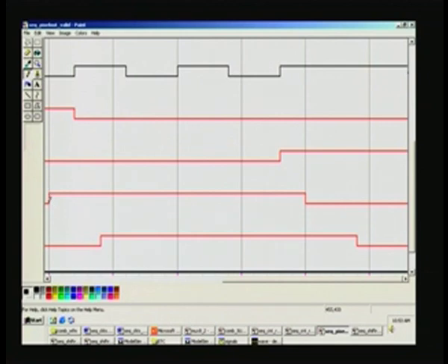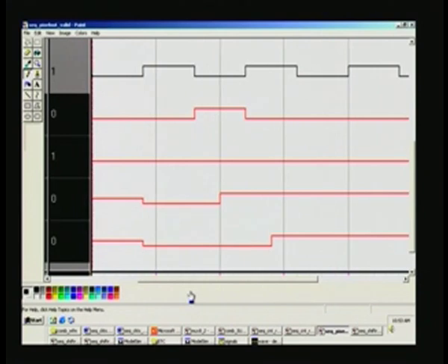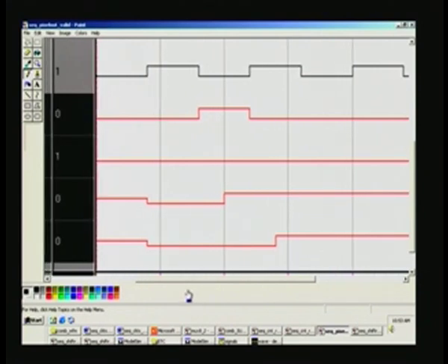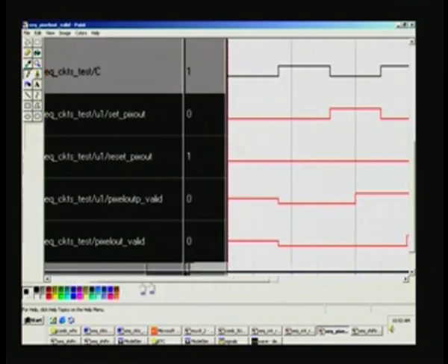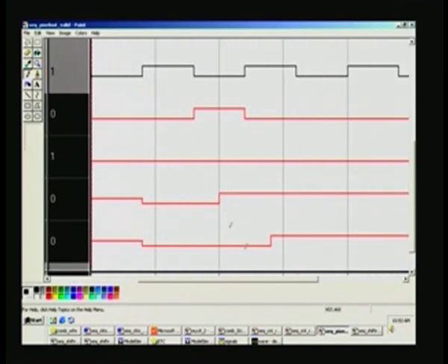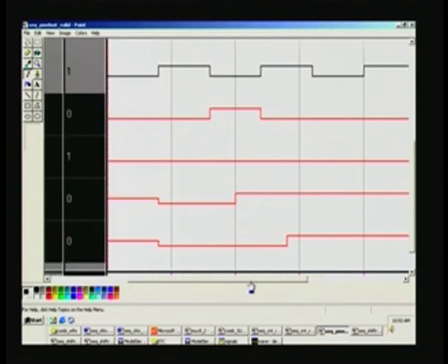So, you have seen pixel out P valid and this being staggered just by 1 clock pulse, and if we explain this pixel out valid, why it is happening here and why it is going low here, that would complete this 2 registers used as in a pipeline, or it's just to create a delay as such. So, now let us see why it is going high. It is going high here, right. Let us find out why, and how.